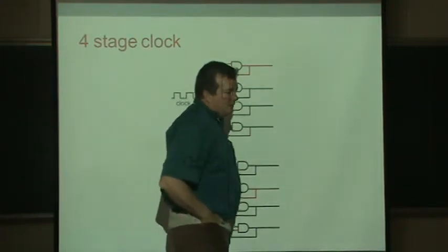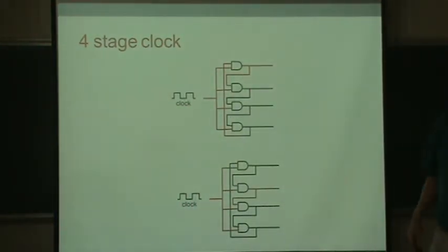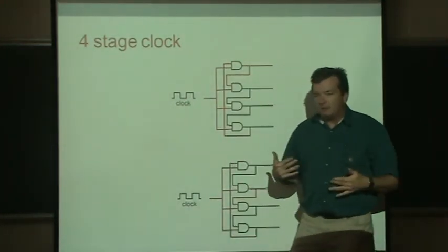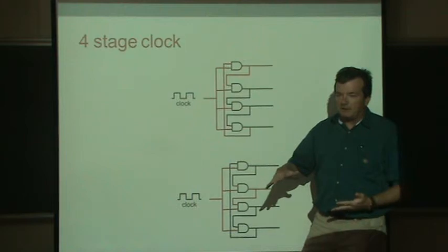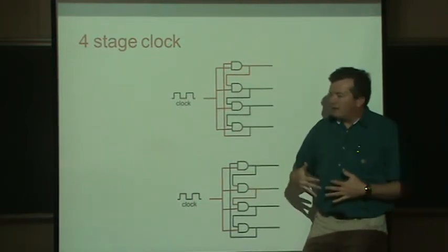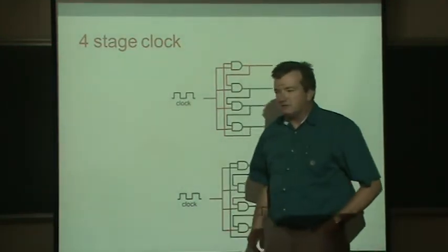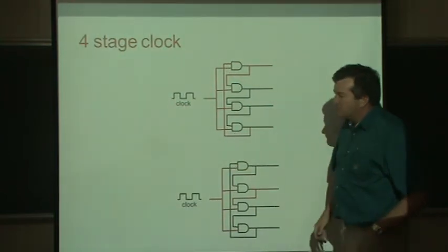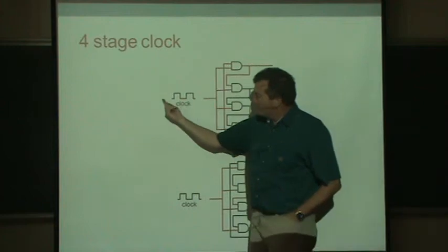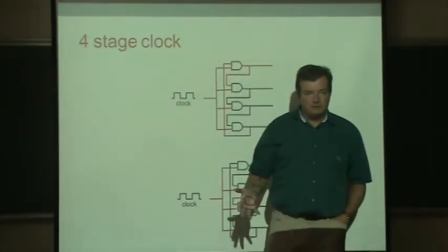So this would be why the fundamental design of the clock says that no matter what stage you're doing, the fetch, the decode, reading the inputs, executing the mathematics, and the final step of writing the results back to memory, whichever one of those 5 steps, if it's a 5-stage processor with 5 stages to run each instruction, whichever step takes the longest, we would have to set the clock pulse to be as slow as the slowest stage.